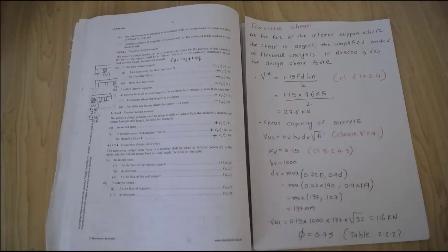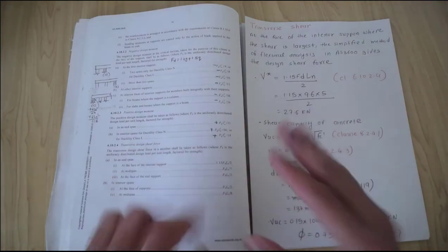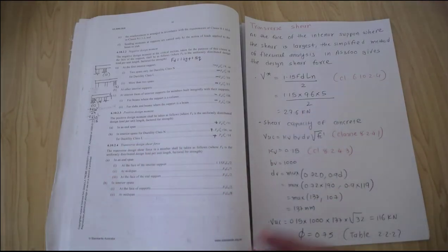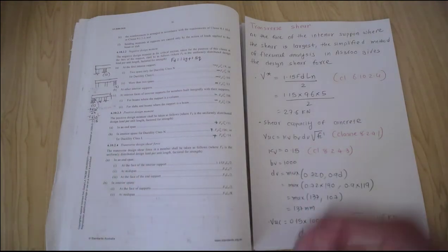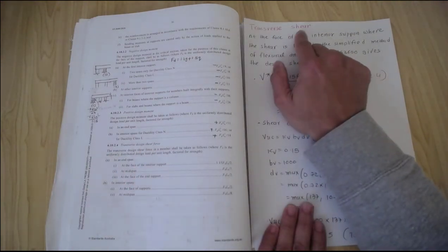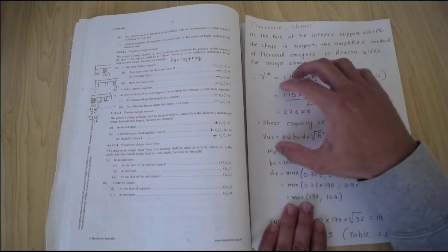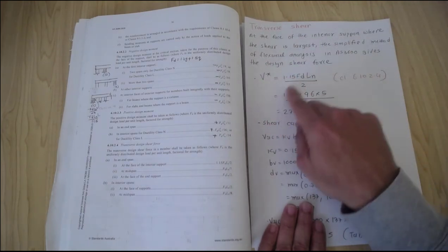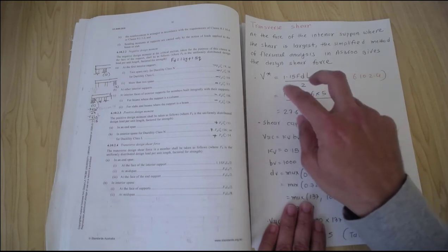We finished the calculation of reinforcement in the x direction, reinforcement in the y direction, and also the calculation for finding the depth of the slab, and we also did the deflection check. So now we are going to do one more check, which is transverse shear, to see whether we require fitments or not. First of all, we're going to calculate the design shear force.